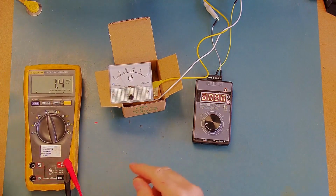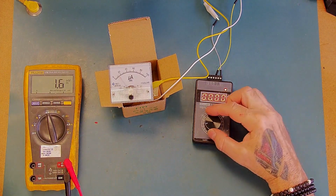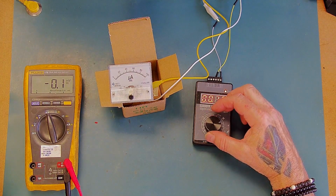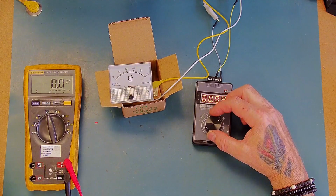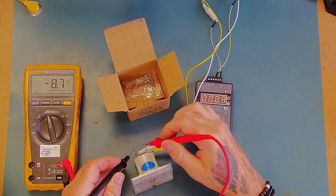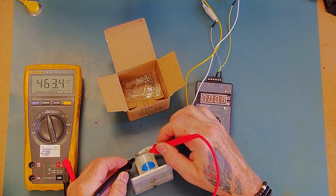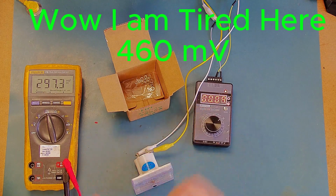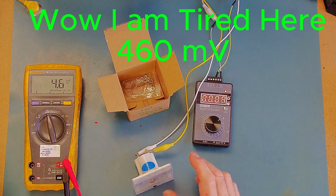So let's get the Fluke out. I've got this set to DC millivolts, so I'm just going to crank this up till we get to somewhere near full scale. That's a little bit over, we'll go a little bit under to start with. So measure the voltage across there now. So that's about 260 millivolts. So we'll use that as our reference.